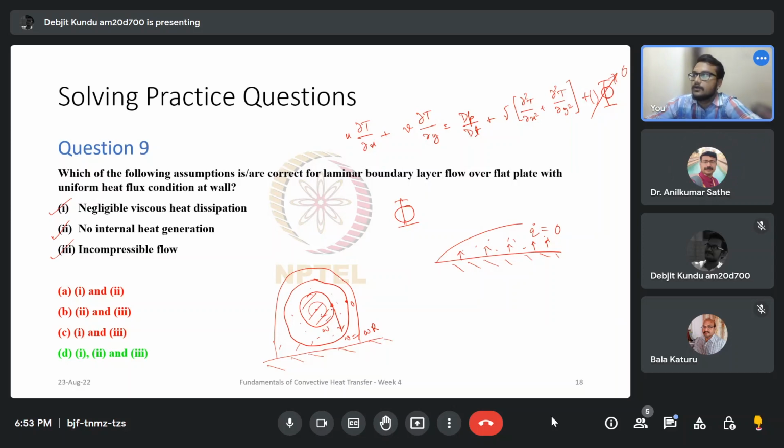And within this small distance, there is a very high velocity gradient created. And mind you, this delta is also very low. This delta is very, very low, the distance between the shaft and the bearing. There is a very thin film of liquid in between, and within that thin film there is a very large velocity difference.